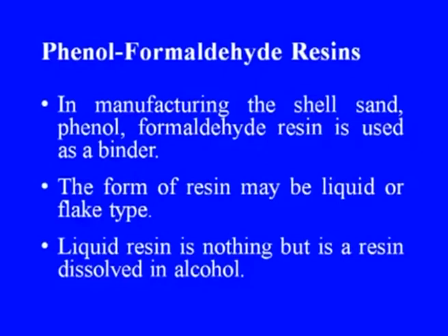Phenol formaldehyde resins. In manufacturing shell sand, phenol formaldehyde resin is used as a binder. The form of resin may be liquid or flake type. Liquid resin is nothing but a resin dissolved in alcohol.